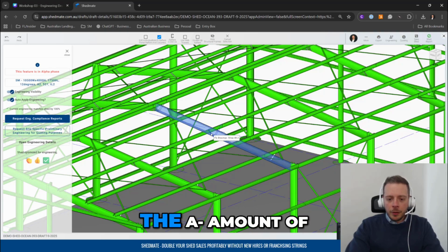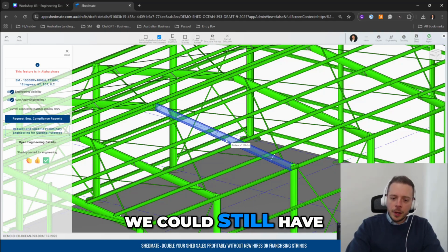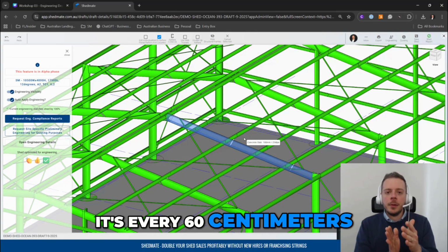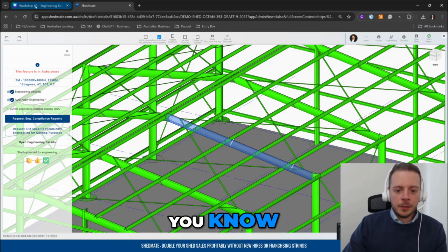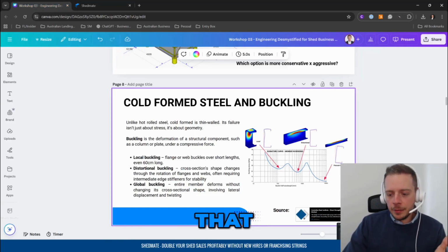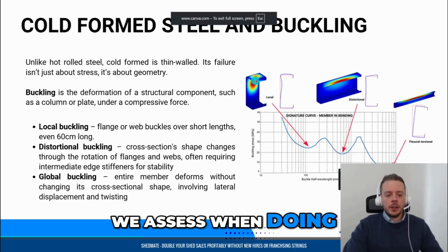No matter the amount of fly bracing I put here, we could still have a local buckling because it's every 60 centimeters. And we don't want to do bracing every 60, or 600 millimeters. That's not practical whatsoever. So this is something that we assess when doing the analysis.